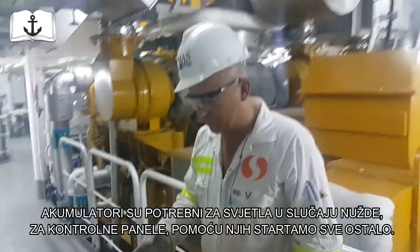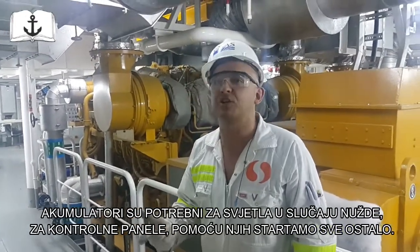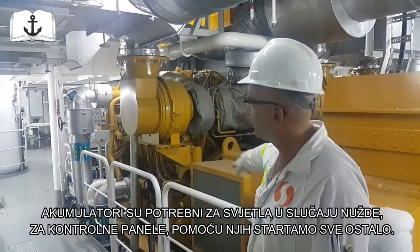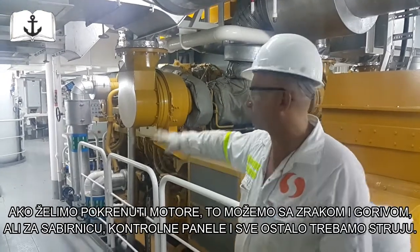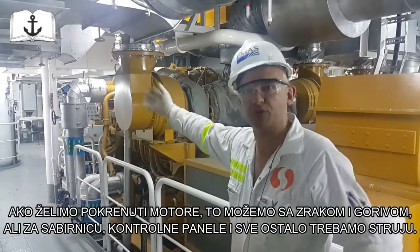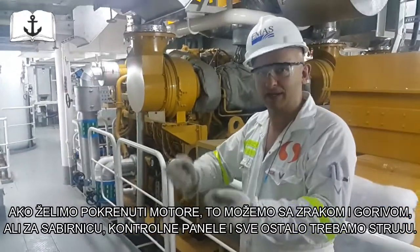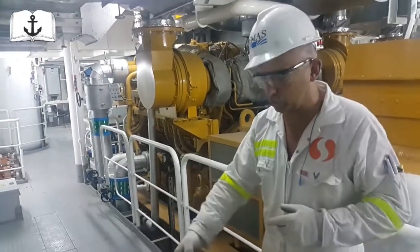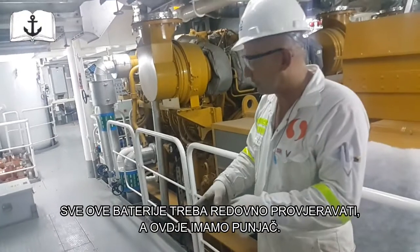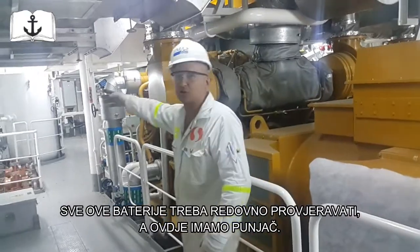The thing is, you need the batteries to keep the emergency lights, for example. You need the batteries to keep the emergency control. If you want to start up everything from the beginning, you can do it with the air and the fuel that we have all the time. But the problem is, all the breakers, these cubicles that we showed on the bus bar, that connect the generator with the bus bar and the outputs, they need control power, and the control power is also coming from these ones. It's like 24 volt now. And all these batteries, it might be 12, depends on the construction of the ship, but all these batteries should be checked, and we have the chargers there.